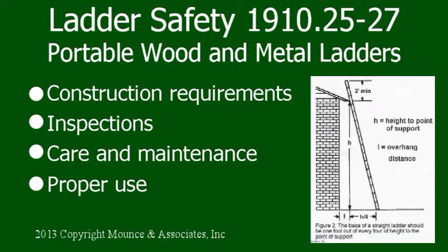Ladder safety. Portable wood and metal ladders. When using a ladder, always make sure you choose the right ladder for the right job. Before using the ladder, make sure it is in good condition.